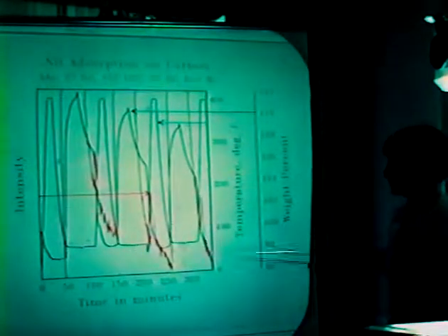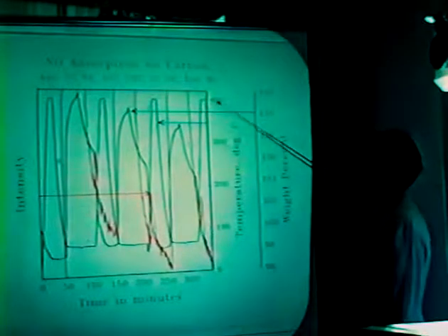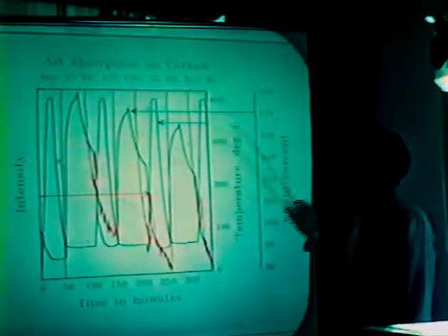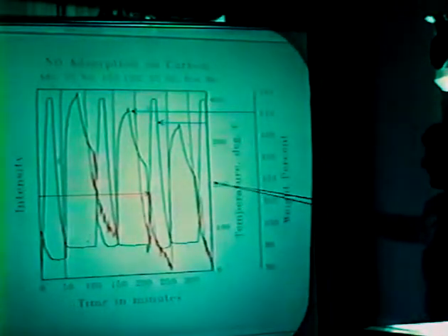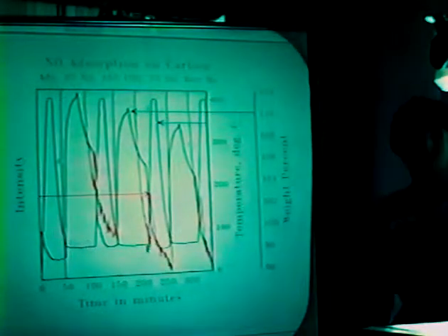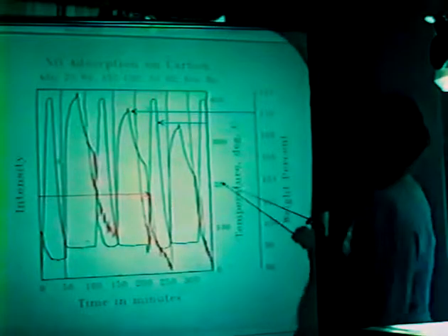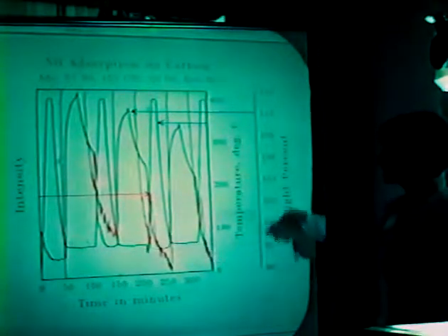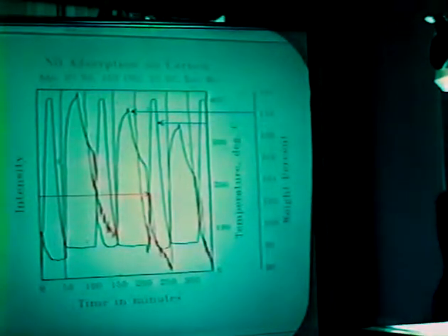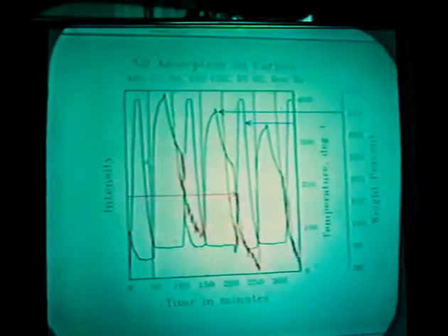Subsequent to this work, we have considerably lowered the desorption temperature. We now find that since the maximum desorption temperature is about 140 degrees C, we only routinely go up to 200 degrees C, minimize this loss here, and additionally minimize an already small loss in adsorption capacity.